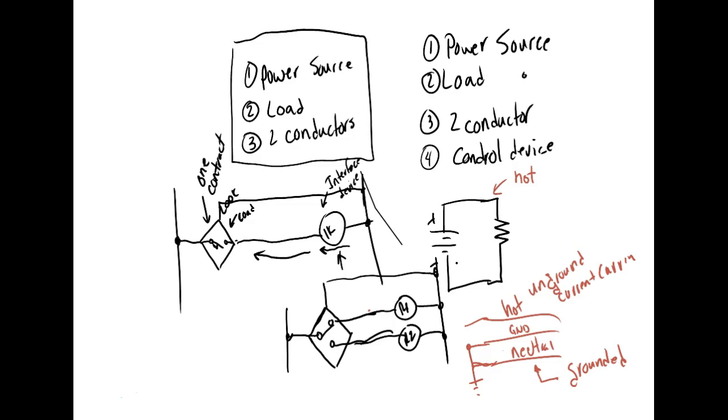Don't understand that? And how can you tell? Well, you can get an ohmmeter and put it across between common and normally open. This is before you put power on that side. If it measures 0 ohms, that's the one you don't want to use. Yeah, everybody understand? Now I think the way it's been working out, I've already done it. I think the one on the right is the one we want to use, right? Yeah, the 2 relays. I think the one on the right is the one you want to use. But you can do that real easy.